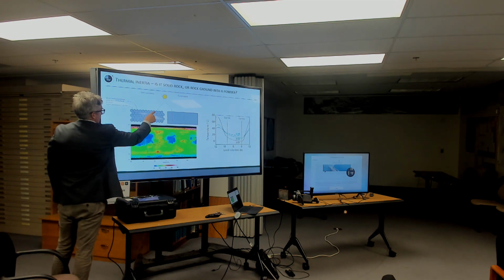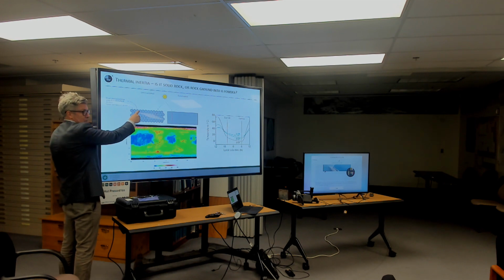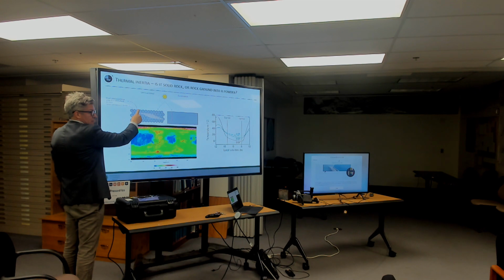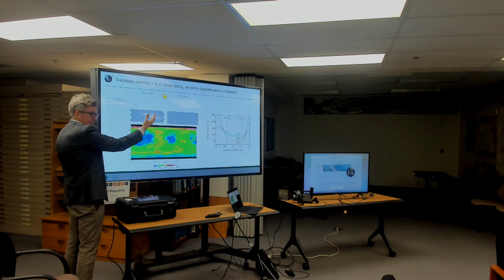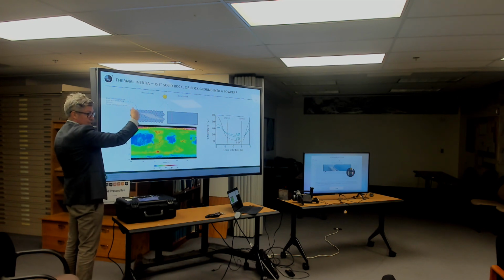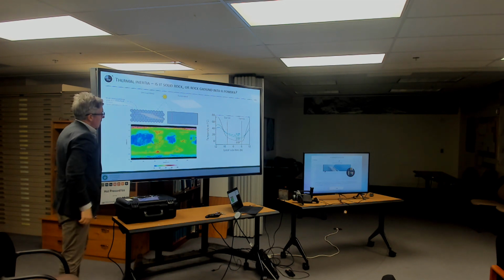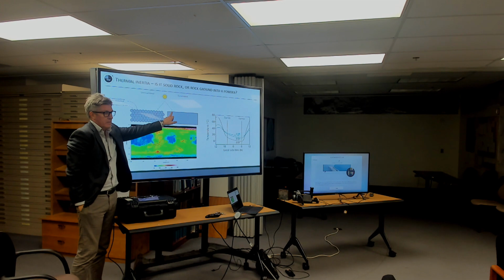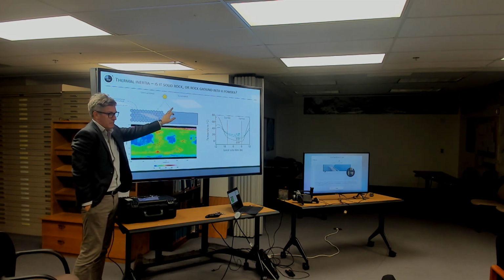So if I'm shining sunlight on this pile of granular material, and it's accumulating at the surface but isn't being conducted very effectively, then I'd expect this surface to heat up quite effectively, because all of these photons, all of these joules of energy are just going to accumulate near the surface, because this stack of stuff isn't very good at shipping it to depth. Whereas on the other side, I would expect the surface to heat up less, because it is efficient at getting rid of the excess energy from the surface down.